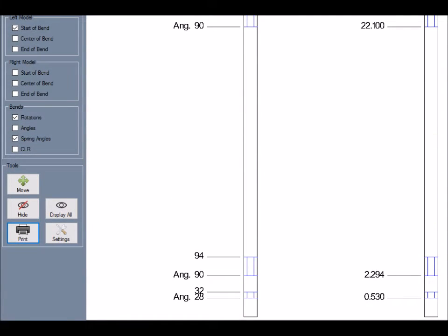The next thing that we do is our computer CAD software takes the verified three-dimensional model and then it creates a two-dimensional layout which provides sort of a template for us for the tubing bender. And what it does is it tells us where to start the bends, where to end the bends, and where to rotate the tubing, how far to rotate it.